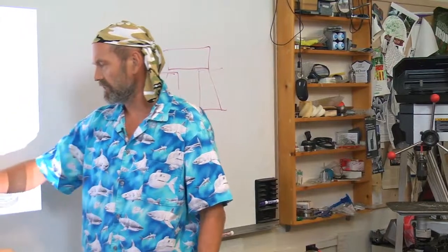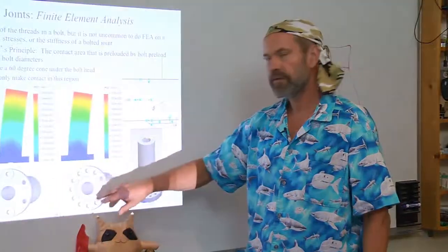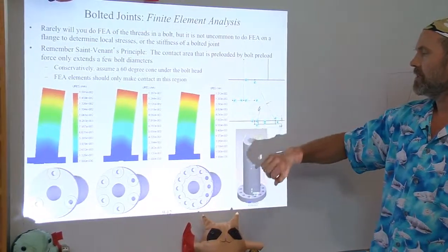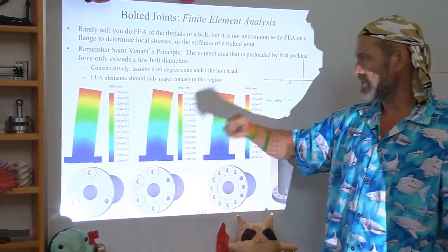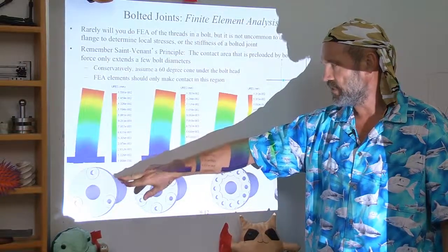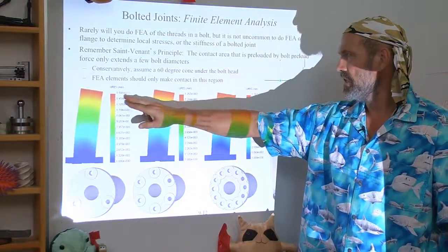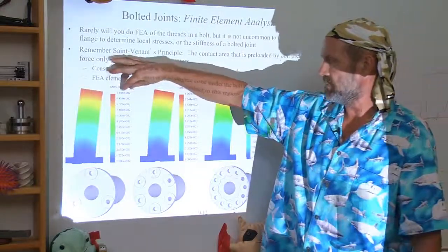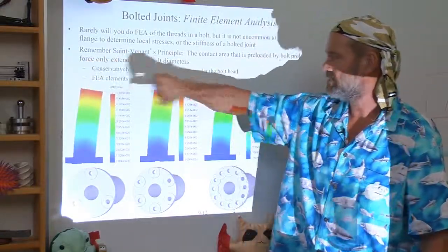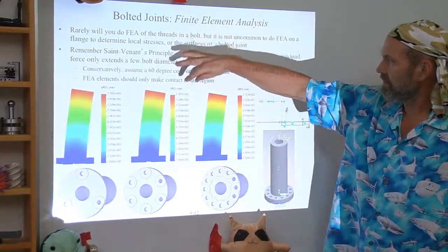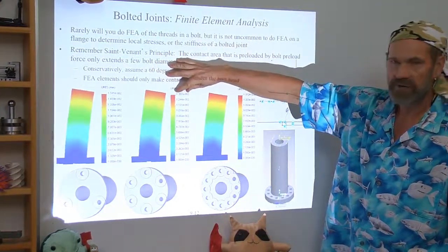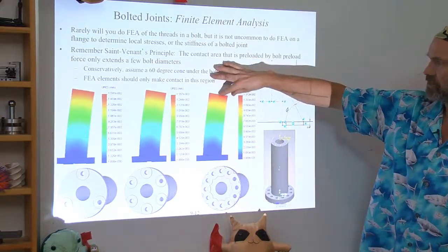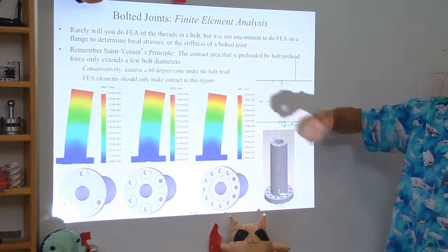Hence, with 6 and at 12, they actually all overlap. And what this finite element analysis is showing us on a relative basis is that the 3 bolts give me an average of 16 microns of deflection for the load that was applied here. 6 bolts gives me 14 microns of deflection, and then the full 12-bolt array gives me 13 microns of deflection.